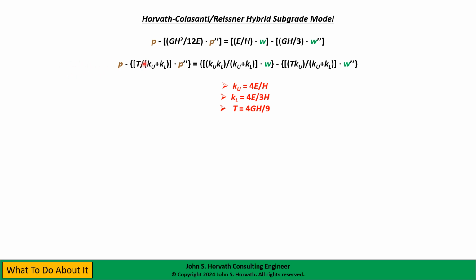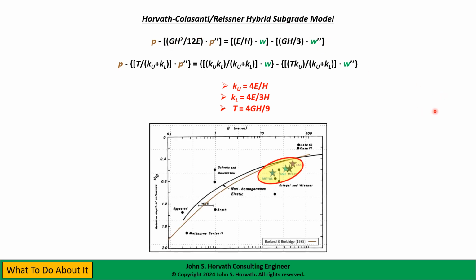So we program the mechanical model in the structural software, and then we come up with the spring constants and things like that. We can relate them to soil properties and problem parameters using the elastic continuum model. And we've applied this. This is not just a research idea. We've applied this to 4 case histories, the 2 buildings on the MIT campus,